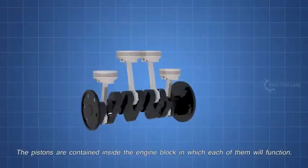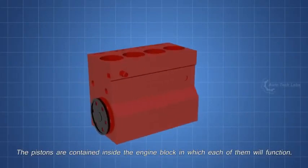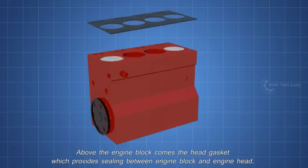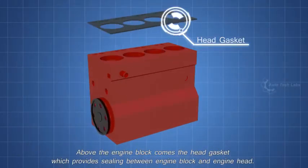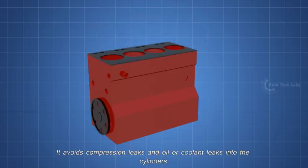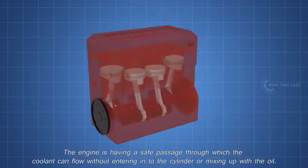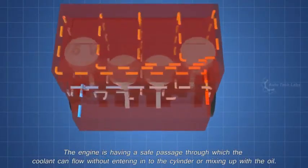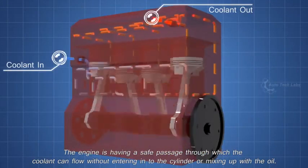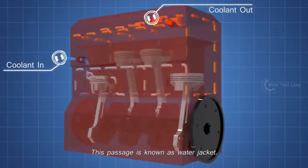Now, let's see how these parts work together. The pistons are contained inside the engine block, in which each of them will function. Above the engine block comes the head gasket, which provides sealing between engine block and engine head. It avoids compression leaks and oil or coolant leaks into the cylinders. Above that comes the engine head. The engine head has a safe passage through which the coolant can flow without entering into the cylinder or mixing up with the oil. This passage is known as the water jacket.